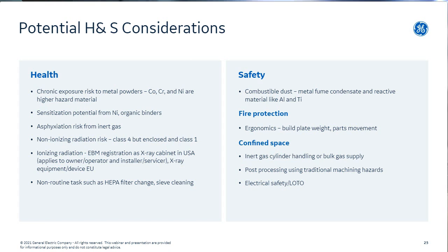EBMs create an ionizing risk. X-rays are generated, not much, but in some jurisdictions you need to be aware that you may need a specific permit to operate the machine and have a radiation safety officer who helps you with meeting the requirements. And there are non-routine tasks, as I said, like changing the filters, that you do from time to time. Things that we do frequently, we tend to do very well and thoroughly, unless we try to figure out how to make this better, and then sometimes it ends up in something that's not working very well. But infrequent things, not trained so often, may impose some risks.